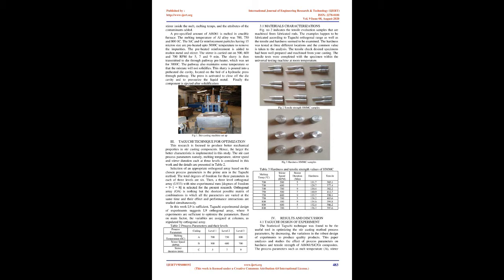A significant concern with the stir casting method is the separation of reinforcing particles, which is due to the settling of reinforcement particles during the melting and casting method. To avoid settling of particles, a motor-driven stirrer can be used. The final distribution of the particles in the solid depends on material properties and process parameters like the wetting condition, intensity of mixing, relative density, and rate of solidification. The distribution of the particles within the molten matrix also depends upon the geometry of the mechanical stirrer, stirring speed, the position of the mechanical stirrer in the melt, the melting temperature, and the characteristics of the particles added.